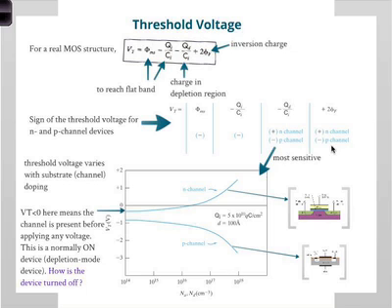And clearly, if you look at these 4 terms, of course you want to control, like I said before, the threshold voltage very well. You don't want it to be too high, you don't want it to be too low. And if you look at this equation, what are the parameters that you can control? The only real parameter you can control, I mean, let's look at them. So the work functions you can't really control very much. There's only a few. You don't use metal, so you have polysilicon with some doping, and the Fermi level is pretty much fixed, because it's very heavily doped. Now, on the other side, it has to be lightly doped, so you don't have much control either. So this is out of the question, pretty much.